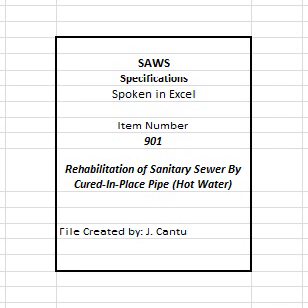G. The curing shall be accomplished by utilizing hot water under hydrostatic pressure in accordance with the manufacturer's recommended cure schedule. After the tube is cured, the new pipe shall be cooled to a temperature below 100 degrees Fahrenheit (38 degrees Celsius) before relieving the internal pressure within the section. In addition, care shall be taken during cool down so that a vacuum will not develop that may damage the newly installed pipe.